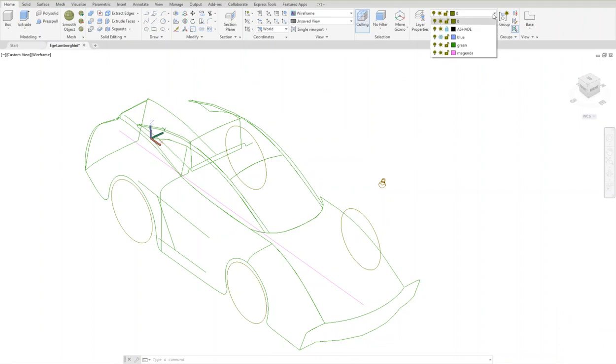When you move your cursor over to the corner, there is a layer command available on the ribbon. When you look at it, one of the layers is auto shade, it's locked, and the top layer, the current layer, the default layer is 0. It's set to green, but we're not using the by-layer setting of the color. We're using red color for the current color.